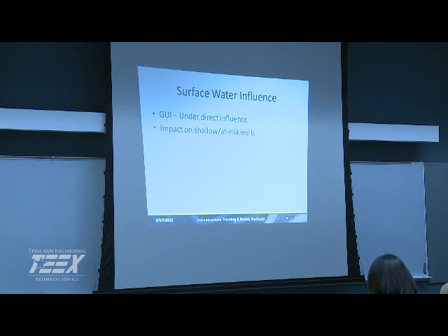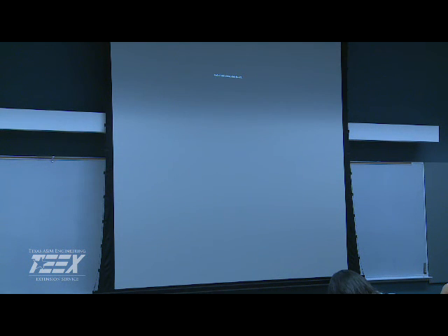We talked about GUI, groundwater under the influence. If you have a shallow well, and every time it rains you can tell your water quality is changing, pH is changing, turbidity is changing, then you're under the influence. Especially real shallow wells, real close to water sources, can fall under the GUI. Here, if it's in a karst, probably not, a high probability not. But if you are, then you have to start looking at the surface water treatment rule and at your pathogens like Giardia and crypto. Ultimately, you need to evaluate what your surface water quality is in that area if you're under the influence. And that is groundwater production.